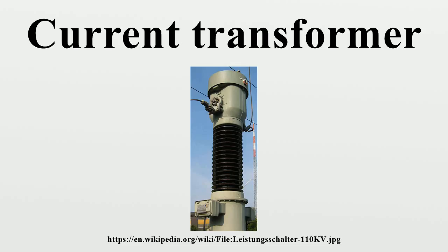Safety. Current transformers are often used to monitor hazardously high currents or currents at hazardously high voltages, so great care must be taken in the design and use of CTs in these situations. The secondary of a current transformer should not be disconnected from its burden while current is in the primary, as the secondary will attempt to continue driving current into an effective infinite impedance up to its insulation breakdown voltage and thus compromise operator safety. For certain current transformers, this voltage may reach several kilovolts and may even cause arcing.